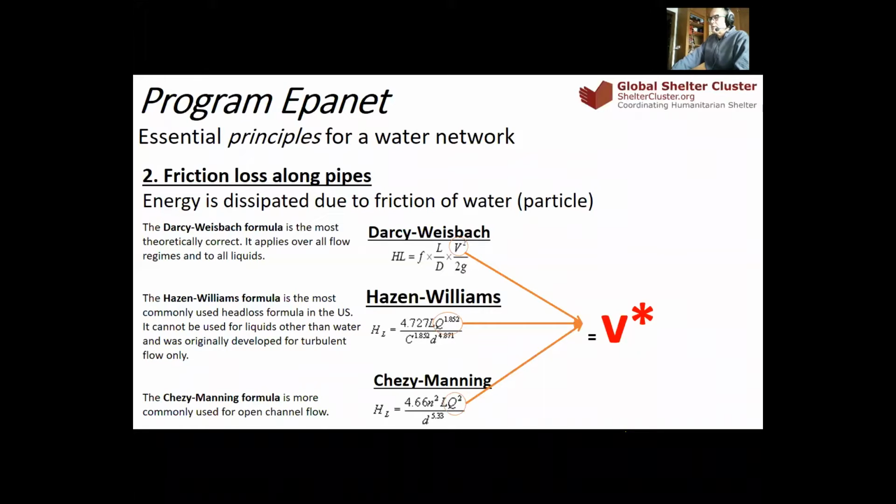I apologize. So if you have a very high tank, let's say on a mountain, it means your water will have a very high amount of energy, potential energy. We are going to speak about that later. So at the tap stand, you are not allowed to have too much energy because you might destroy the pipe, you might destroy the tap, and if not, the water will spit out of the tap too quickly.